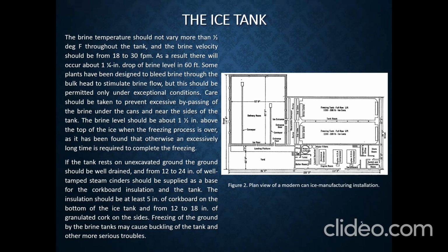The brine level should be about 1 1/2 inch above the top of the ice when the freezing process is over. It has been found that otherwise an excessively long time is required to complete the freezing.